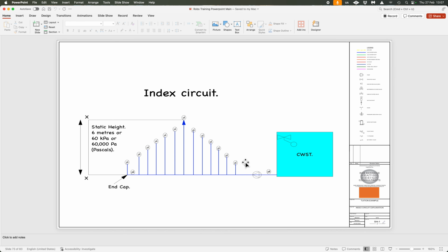But that's the way I try to visualize it, and I think that was very, very helpful to engineers to understand. All you need to do is overcome the resistance of that one, and it'll get over the resistance of all of these, whether there's 6 aside here or 600 aside. It doesn't matter. So whether you're in a 2-bedroom flat, for argument's sake, with 4 emitters or something like that, or in a 200-bedroom hotel with 2,000 emitters, it makes no difference. As long as you find the index circuit, which is the highest resistance, that is how you would size your pump. That is it.